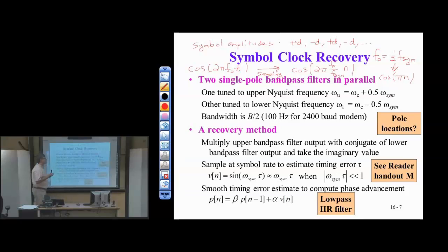Okay. So the highest frequency that we're going to see, again, the pulse shaping can expand this. If we use a raised cosine pulse, then the actual frequency content at baseband will be 1 plus alpha times half the symbol rate, where alpha is between 0 and 1. But we are going to include half the symbol rate. We're confident about that by the time we see the transmitted signal in the receiver.